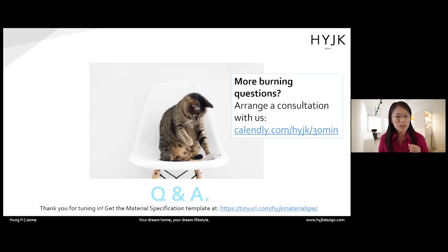So I would suggest getting a very good residential sealer for marble, and or the commercial sealant that they use. For example, at Takashimaya, they have the commercial sealants. This will last a lot longer, so you don't have to keep polishing the marble in your bathrooms or in your living room. Usually they come very shiny, very slippery and polished, and yes, sometimes you have the powder that's residue from the polishing. So sometimes you would see that.